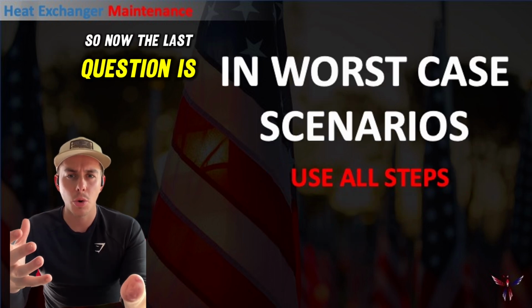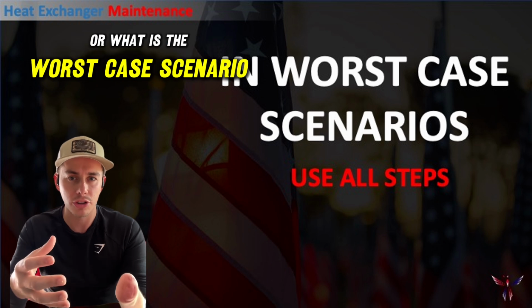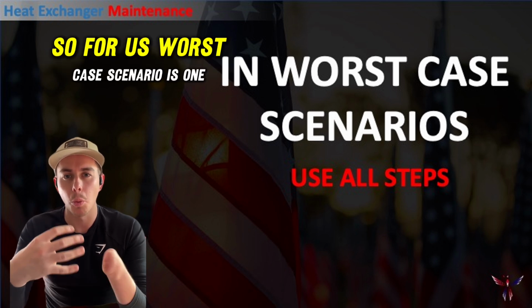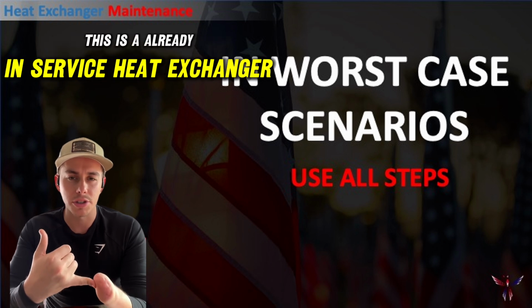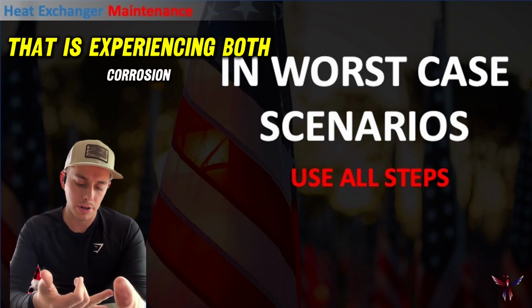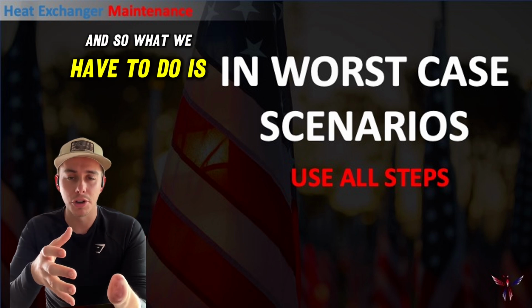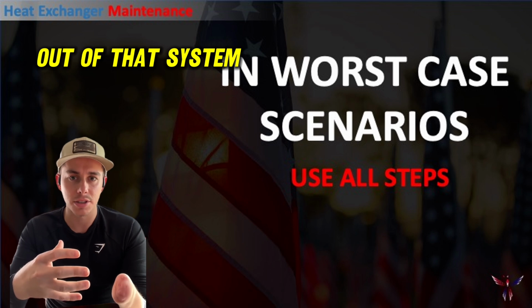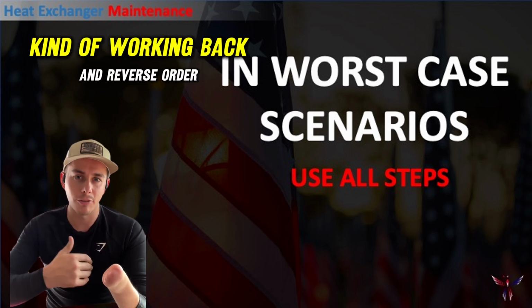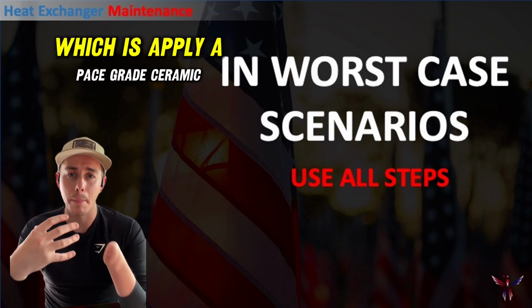So now the last question is, what is the worst case scenario? So for us, worst case scenario is 1, this is an already in service heat exchanger that is experiencing both corrosion and fouling. And so what we have to do is, 1, we have to clean all of the fouling out of that system. And then the second would be, kind of working back in reverse order, go with step 3, which is apply a paste grade ceramic.